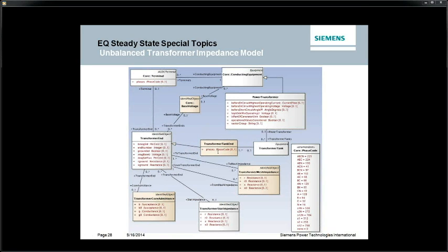So you can go back in and say that a single tank is connected from a primary terminal to a secondary terminal, or from terminals A, B on the high side to the other transformer end, being S1 and S2 in that previous diagram. And of course, the transformer ends are contained within a tank instead of a power transformer. So therefore, you can organize this as is actually built in the field.